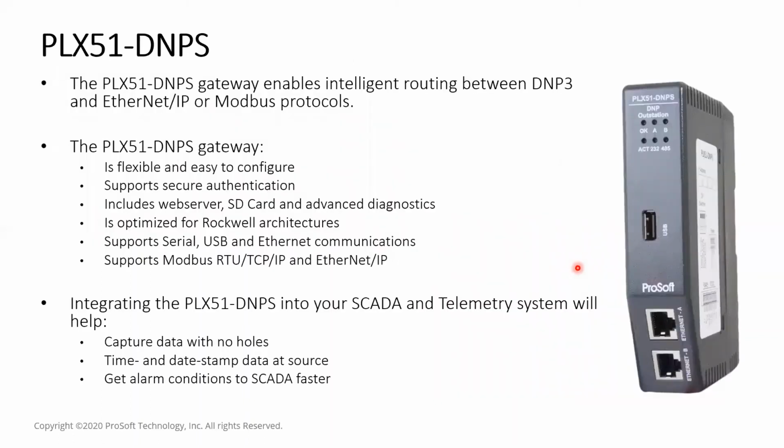Okay, so this is pretty much a summary slide. The gateway enables intelligent routing between DNP3 and Ethernet IP or Modbus protocols. The gateway itself is super flexible and very easy to configure. It does support secure authentication. There is an onboard web server for diagnostics and also an SD card that allows you to reduce your mean time to repair. It certainly is optimized for Rockwell architectures, but it does not mean that it only works with Rockwell. It will work with any controller out there.